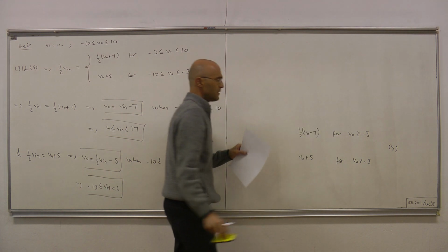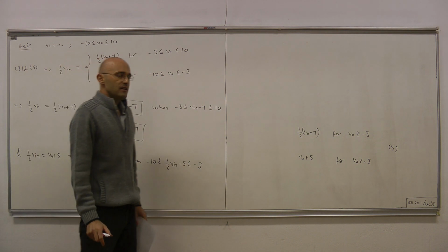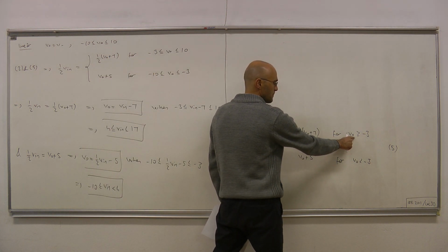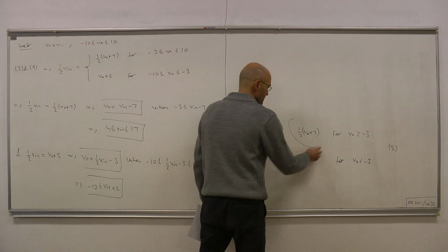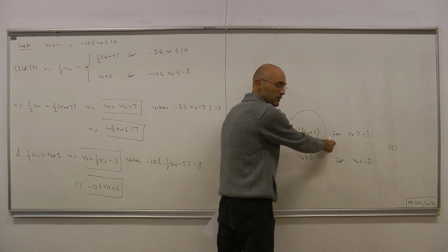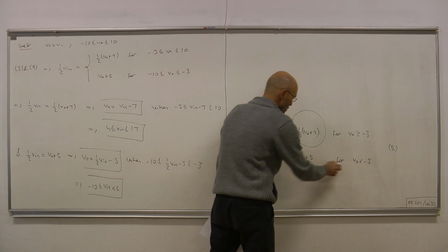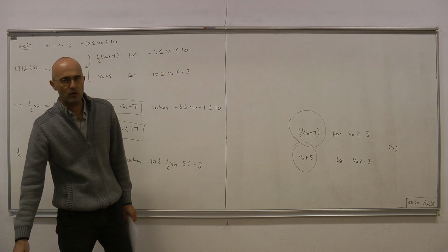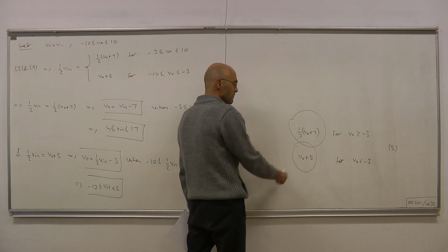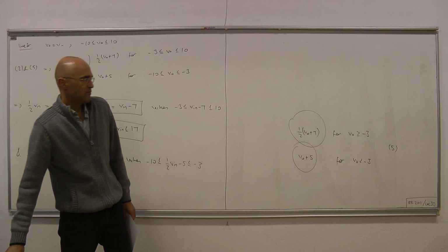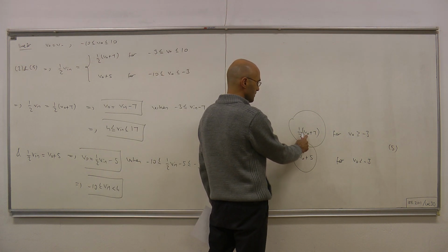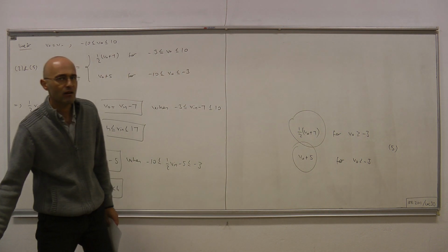Okay. Note that for the positive side, we have V out equals 10 volts. Therefore, this condition holds. That means V minus equals this. Okay. And for the negative side, V out is minus 10. Therefore, this condition holds, and V minus, therefore, equals V out plus 5. Of course, for the negative side, V out is minus 10. Therefore, V minus is minus 5. And for the positive side, V minus is 1/2 times 10 plus 7, so 17 over 2. Okay.